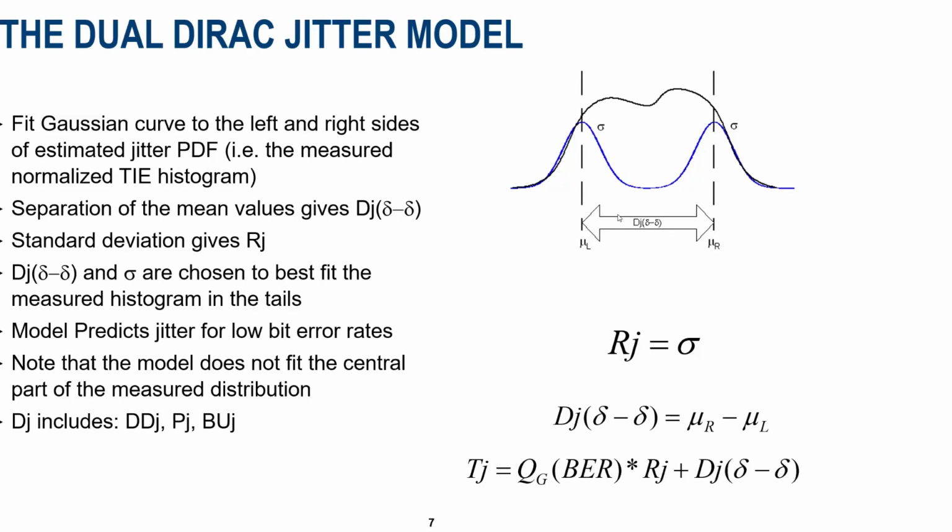And the other problem that you have with this, probably more relevant to what we're talking about here, is that deterministic jitter that comes out of this model doesn't really help understand what the true effect of the insertion loss of the channel has on the timing error. And that can actually be larger or even smaller than what is reported in this DJ number here.